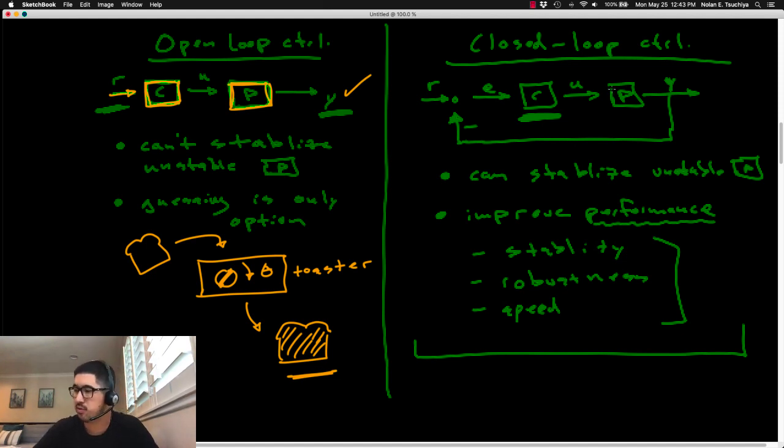I need to be absolutely certain that we understand what the dynamic behavior of a system means before we can actually close the loop around it. So what I'm basically asking is, do we understand enough about the actual plant that we're trying to control? Because if we don't, it's jumping ahead to try and do feedback control if we don't exactly understand the dynamics of the open loop plant by itself.